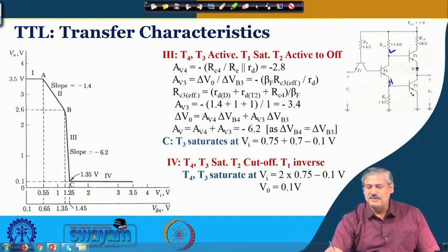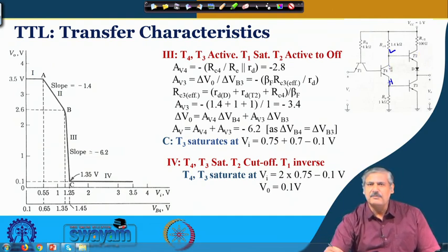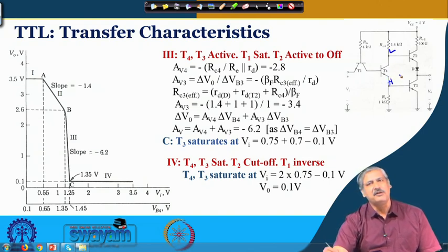So, 0.75 volt, 0.2 volt here, 0.95, which is not sufficient to drive both this transistor and the diode on together. So, this transistor will be off. In that perspective, when one is low, the other is high, and when one is high, the other one is low. So, they remain out of phase, that is why it is called a phase splitter.